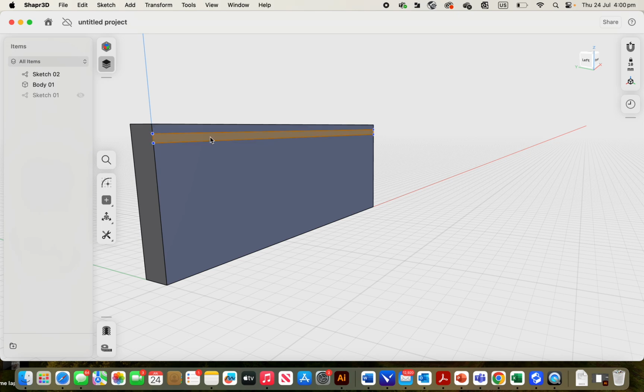highlight the gap between those two lines, all right? And that will be 5 millimeters. Highlight that and left click on the cursor. So these blue arrows appear again. We're going to push that in and create a gap, a groove into the timber that's 5 millimeters deep.